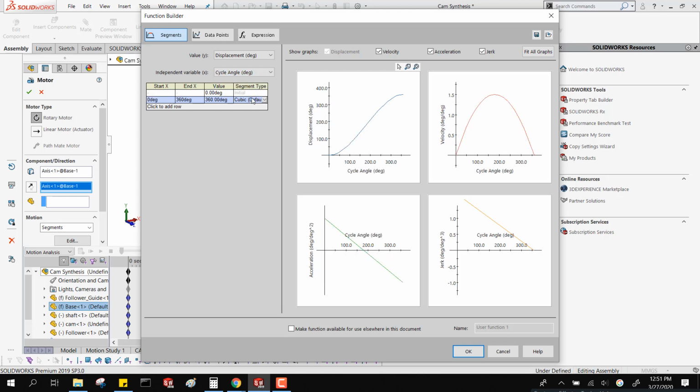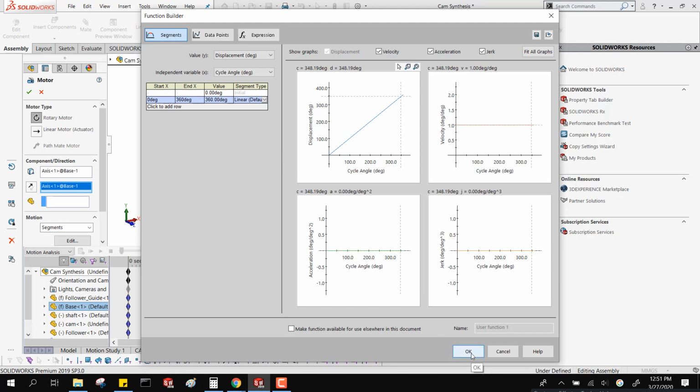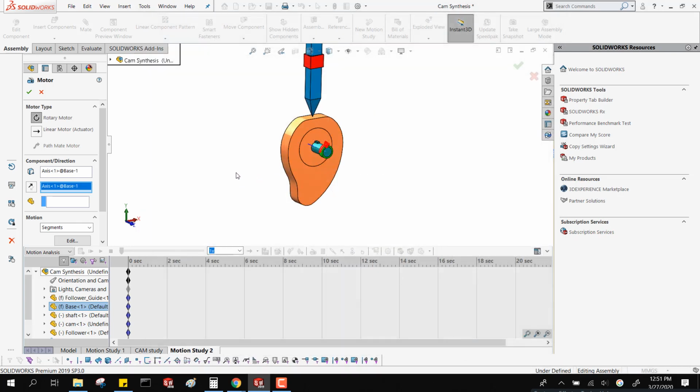So you're entering displacement and it's calculating the velocity and acceleration that corresponds to that? Yes. You could put in acceleration or other factors if you wanted? Yeah, there's different types of things that you can put in here. So I can do it by, all right, do I want displacement, velocity, acceleration? So there's different ways that I can apply the motor rather than just saying, hey, it's this RPM, to get better results. The closer to reality you can get this type of thing running, the better it'll be.